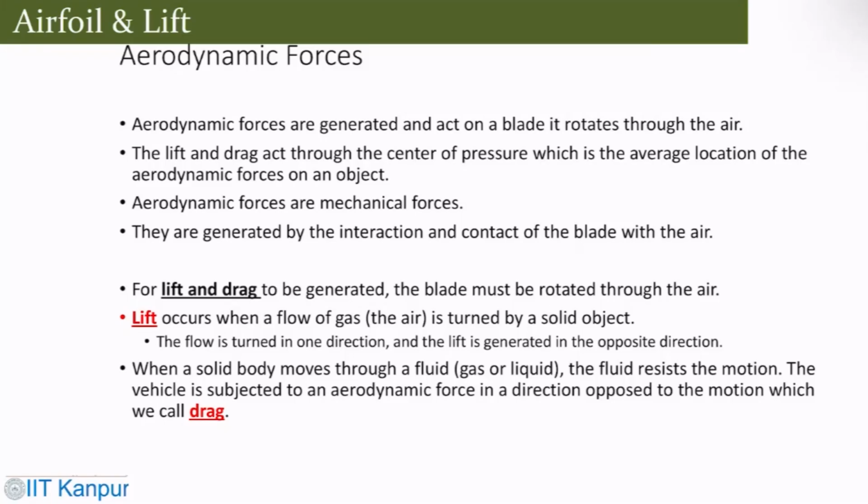Now, talking about the aerodynamic forces. The aerodynamic force is generated when the blade rotates through the air. So the lift and drag act through the center of pressure, which is the average location of the aerodynamic forces on an object. These are mechanical forces, and they are generated due to the interaction, or contact, of the blade with the air.